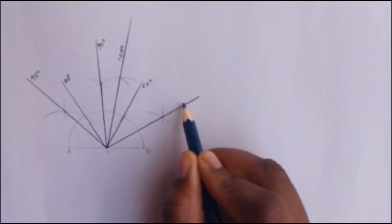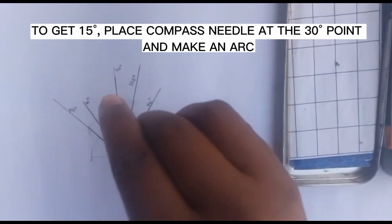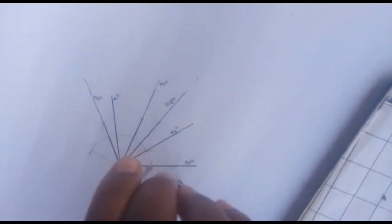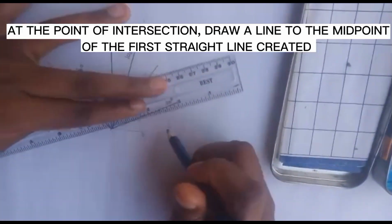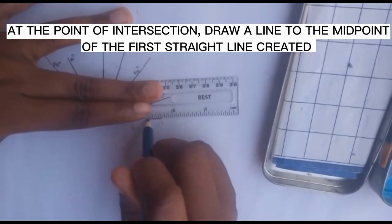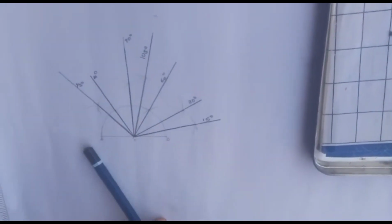I just labeled it. So to get 15 degrees, you put your compass needle here on the 30 degree angle, at the point where you joined the line of 30 degrees, and then you make an arc, and at point B you make an arc as well, and then at the point of intersection, you draw a line from the middle down to this point O, and this is your 15 degrees. So what works here can work here.